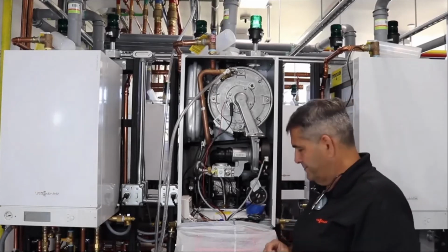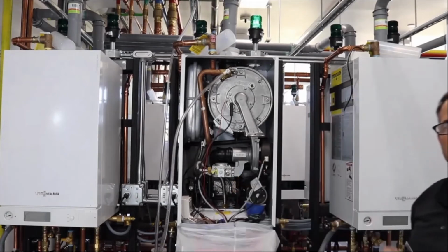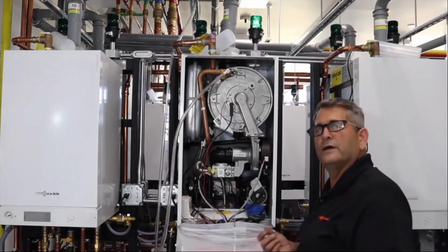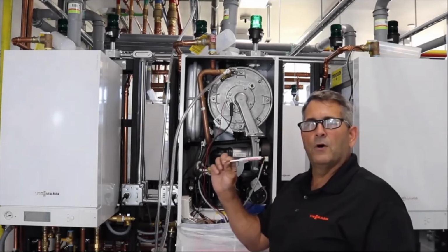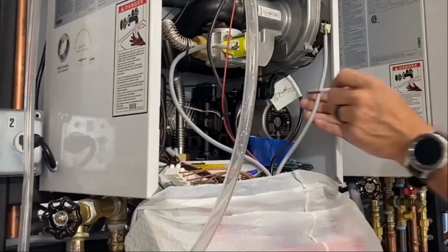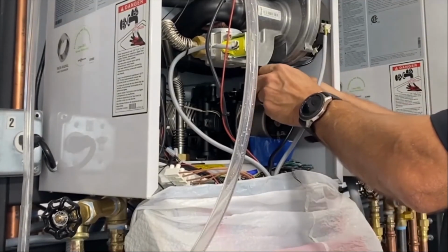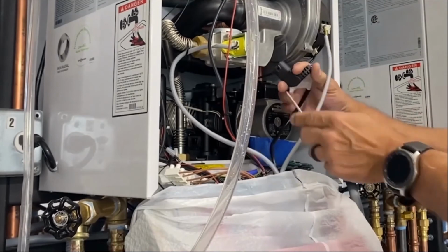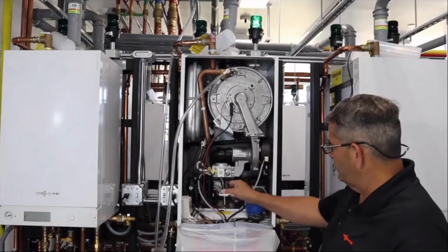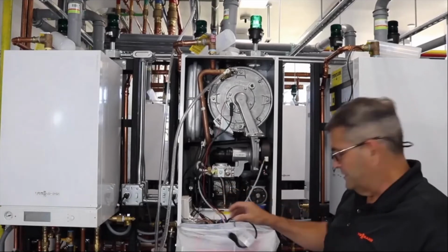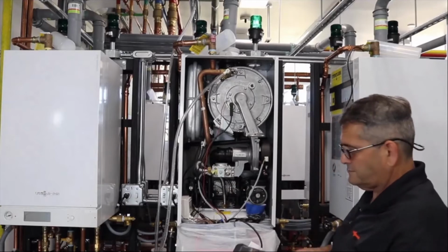or airbound. The other thing we want to check is for 120 volts at our plug. Next thing we want to do is remove the plug off the pump itself, and you're going to need a small screwdriver to do so. And you're going to stick it into the tab here, loosen the hold on part of it, and then pull it out. And what we want to do here is check for 120 volts. So we will have to turn on our boiler and check on 120 volts with our meter.